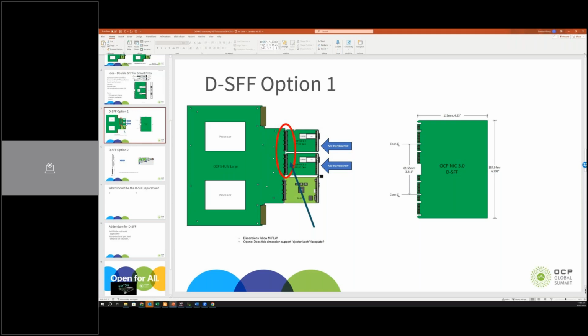So this one is a bit smaller, because there's a little bit of space to the top of the picture, where the power supply bay is. That upper OCP NIC, which is the primary and required NIC, can have a thumb screw. The middle one is called the platform custom zone, and we define a couple of different options. You could put boot devices, or you could put an OCP NIC there, but because of the resulting space, that middle one is the only no thumb screw space.